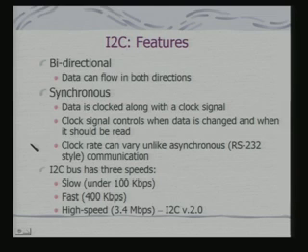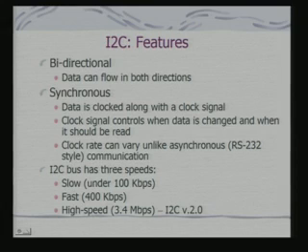What are the I2C features? Here, the data can flow in both directions, but it has got two wires, just the clock and the data line. So, it is not a full duplex communication, but actually a half duplex communication. It is a synchronous bus. So, the data is clocked with a clock signal. In fact, the clock signal controls when data is changed and when it should be read. Okay? In fact, that clock maintains the overall control.